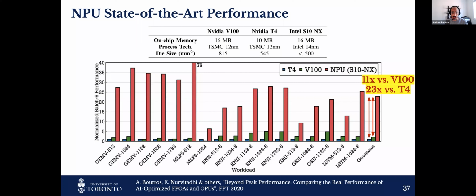We have a study for the end-to-end system where you plug the GPU as a PCIe card in a host CPU, and you communicate with the FPGA over an Ethernet interface, and we measure the end-to-end system performance. And we show that the benefits of using the NPU on Stratix 10 NX are also really big when you focus on the system level performance, not only the compute kernel.